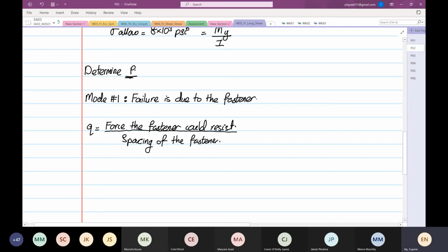So this will be equal to, we are given under single shear is 600. All right, and then you have to multiply by 2. Multiply by 2 down here is not because you have up and down.